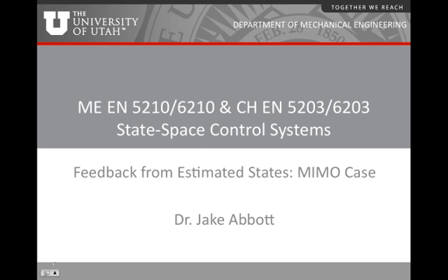In the last few videos in this sequence, we've been talking about using state feedback, if you have full state knowledge, to control our system's eigenvalues. We've been talking about making a state estimator or observer to estimate the states if we don't have full state information. We've seen that we can add those two systems together, and there's this separation principle that lets you design the eigenvalues of the controller and the eigenvalues of the observer separately, and your combined system is just those two eigenvalues combined, which is a really beautiful result.